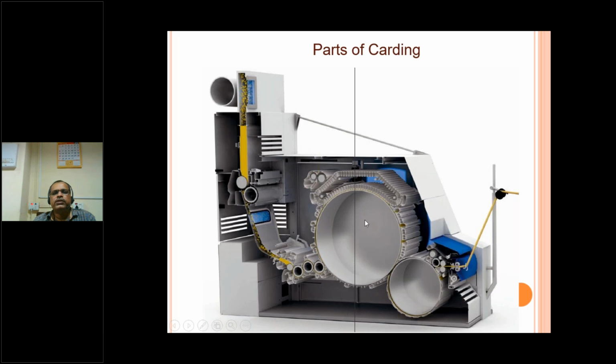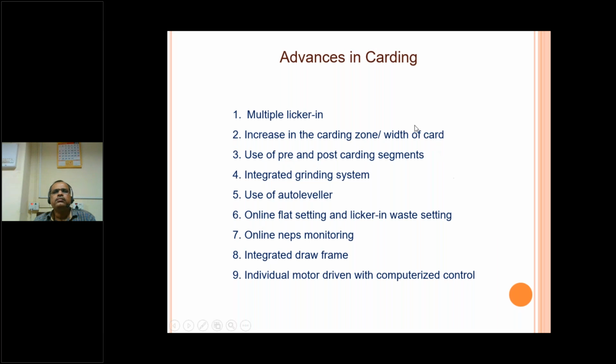This action between the cylinder and the flat is the carding action. Most of the action that takes place is individualization action. Then these individual fibers arranged in the cylinder wire points will be transferred to this doffer wire points. Then it will be collected here and condensed to a sliver form. Continuous sliver will be collected in a can, in a container.